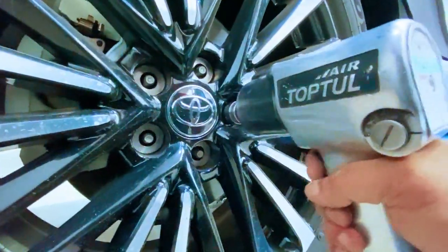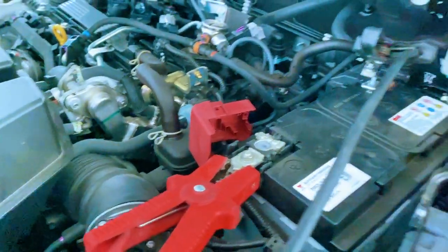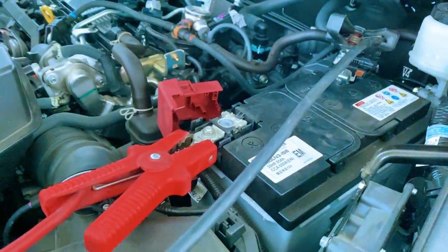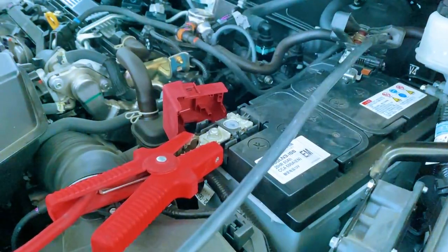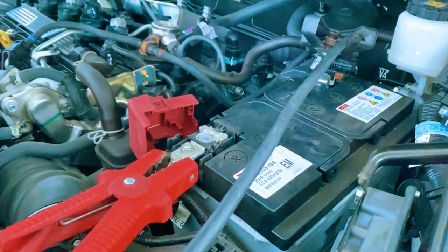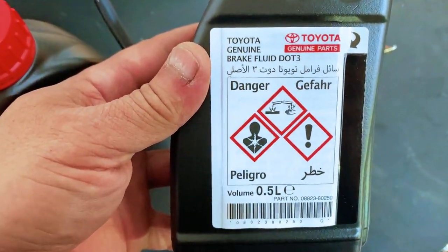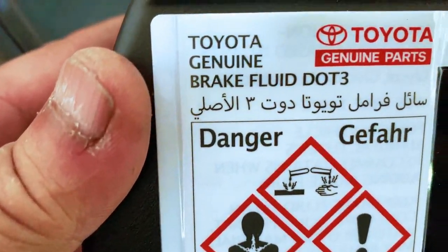9:15. Install the new brake actuator. Now we install the replacement brake actuator. Make sure the mounting surfaces are clean. Position the actuator correctly on the bracket. Tighten the mounting hardware using the specified torque. For this Venza procedure, the actuator to bracket fasteners are tightened to the specified torque, and the actuator assembly is then secured to the vehicle.